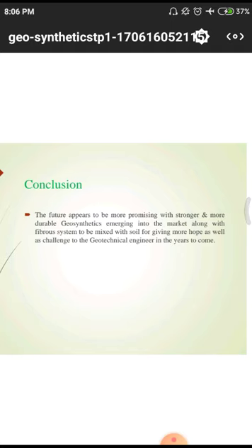But one major disadvantage is that there will be no recharge of groundwater while we are utilizing these kinds of structures. Why? Because the total structures have some geonets and geomembranes. In the case of geonets, there will be some penetration of groundwater, but in the case of geomembranes and layers, there will be no recharge taking place. Due to that lesser quantity of recharge, we have to depend upon some artificial resources for groundwater.